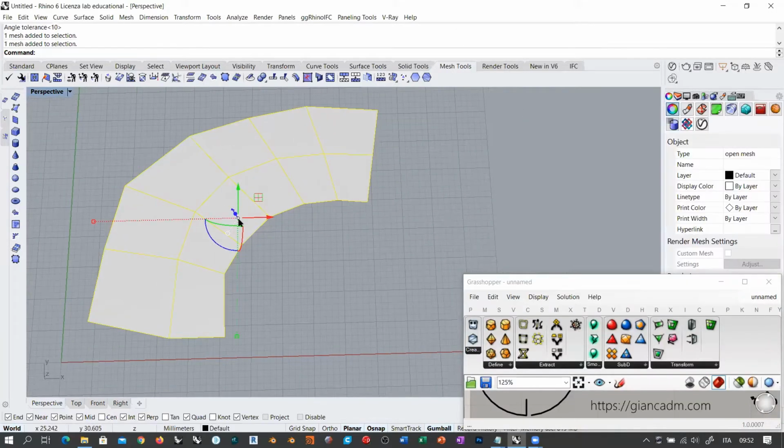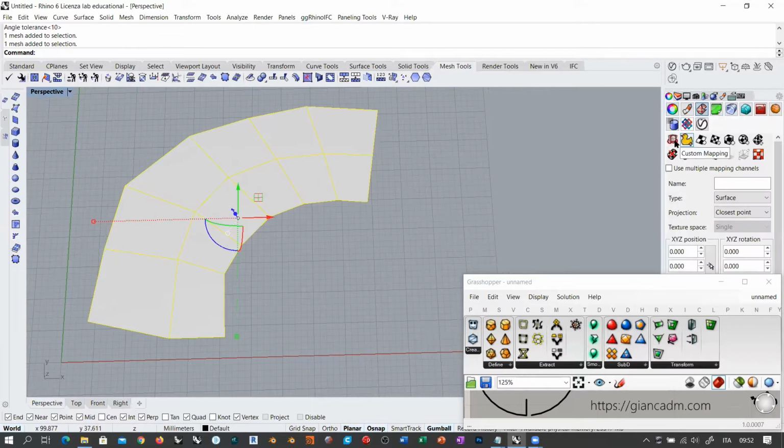If you go on this object and you want to apply some texture mapping, some kind of unwrap, and you want to use the custom mapping and the UV editor, in that case you have access to the UV properties of this mesh. But Rhino is not based on this. And as it is not based on this, we have no modeling possibilities in Rhino to create complex meshes.